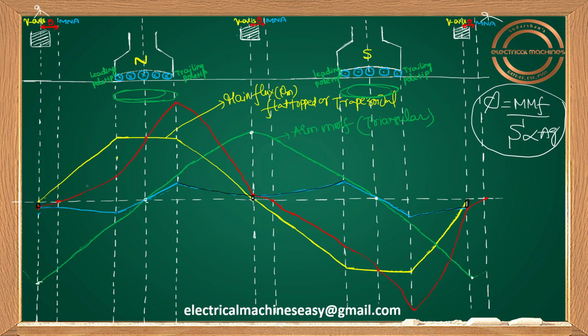Okay. So guys, if you observe clearly, what is the shape of the armature flux you are getting here? If the width of this blue color figure is less, you are going to have a shape like this. What is the shape? I can write this one. It's just like a saddle peak, no? Since the width is more here, I'm getting it like this, but to be frank, you are getting a figure like this. So guys, what is the shape of the armature flux? This one I can say is the armature flux, nothing but Φa. What is the shape of this one? It's a saddle peak waveform.